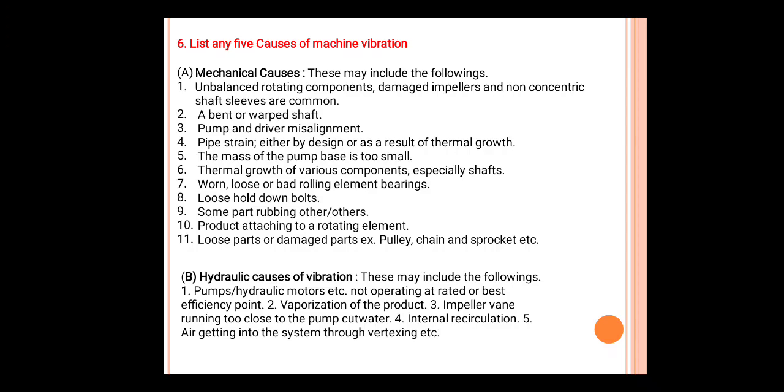And the second type, hydraulic causes of vibration. In hydraulic, what type of causes may be there, we'll see here. These may include pumps or hydraulic motors not operating at the rated efficiency point, vaporization of the product, impeller vane running too close to the pump cutwater, internal recirculation, and air getting into the system through vortexing.